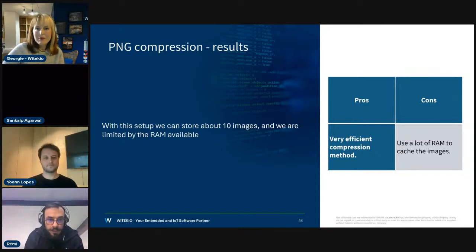It's 18 FPS with this solution. The VRAM usage is about 50%, so we have 1 megabyte. The CPU load was 13%. Everything is cached in the HyperRAM, so we had obviously 6 megabytes of data inside, and we have 240 kilobytes for the VRAM data cached. One other point that is not written here: the caching process takes around 10 seconds when you are booting your application. Afterwards, you don't see anything more, but it's something to take into account.